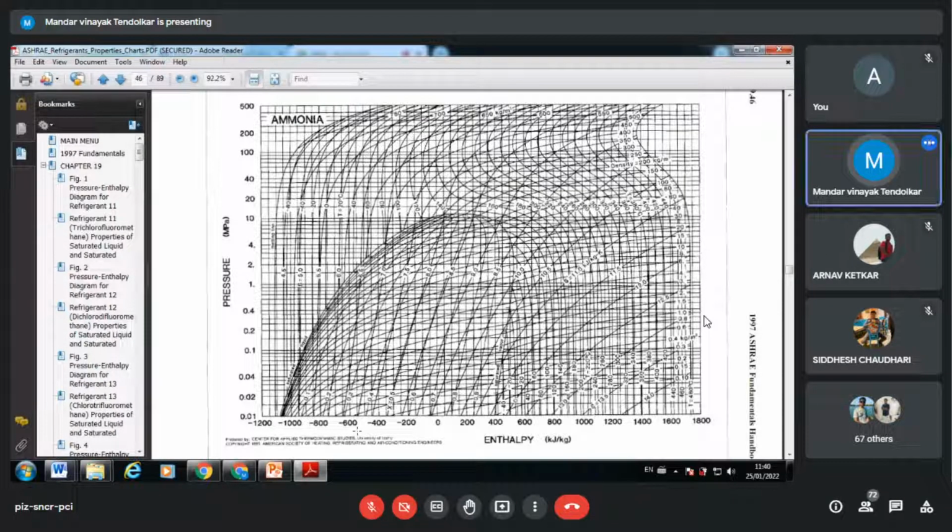Always remember this. Even though the definition says H is equal to U plus PV, that is for the ideal cases. Here you are calculating the enthalpy value of a real substance. This side is the liquid part, this side is the vapor part, ammonia gas and liquid ammonia. How can you assume H is equal to U plus PV is validated 100%?